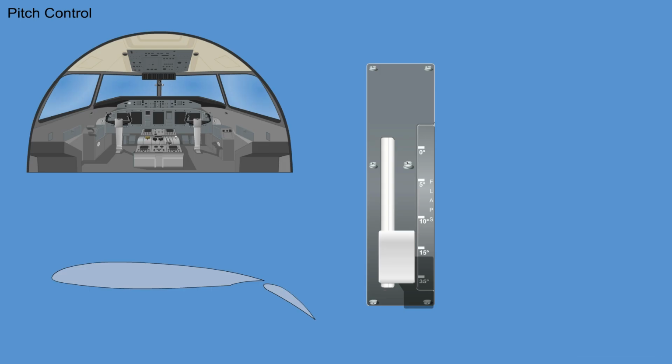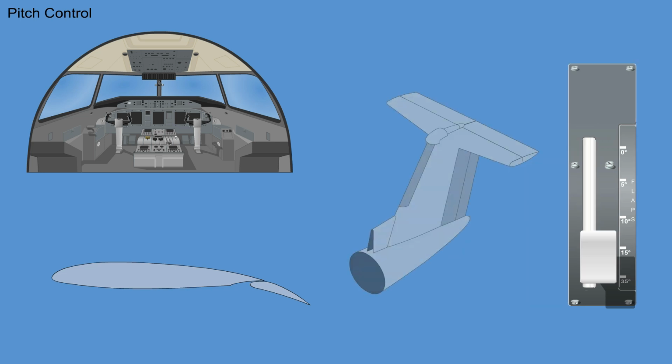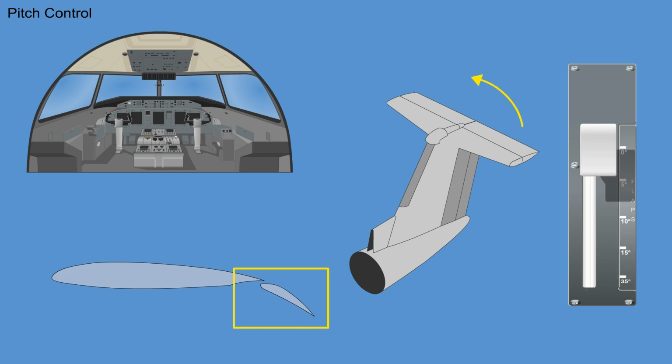During flap extension or retraction operations between 15 and 35 degrees, automatic pitch trim is provided to reduce the pitch forces felt on the control column. The flap auto trim activates and deactivates automatically without any enunciations. Nose down pitch trim is commanded when flaps are extended, and nose up pitch trim when the flaps are retracted.